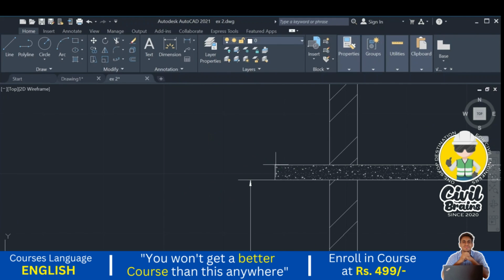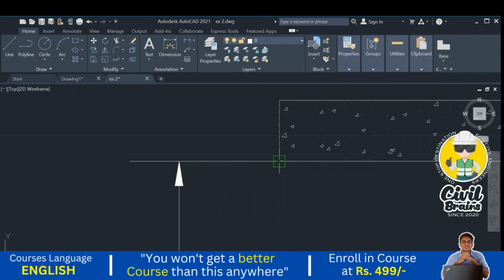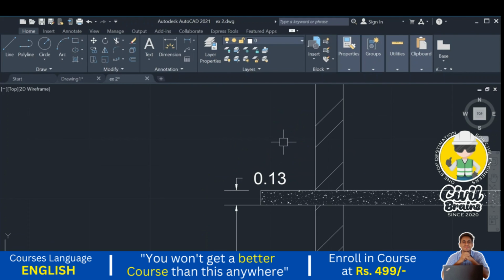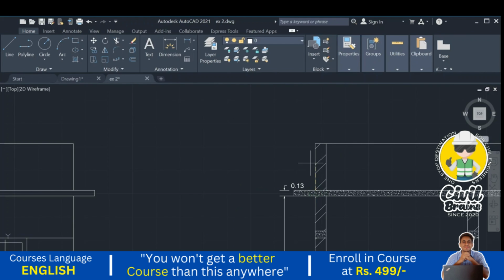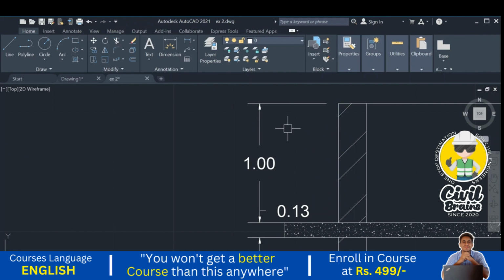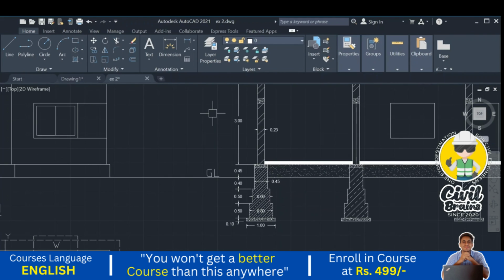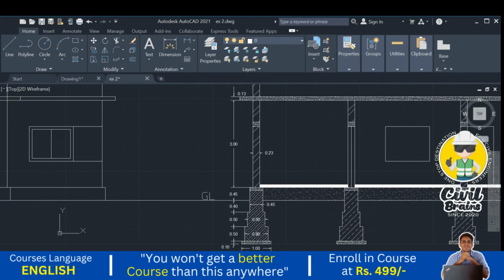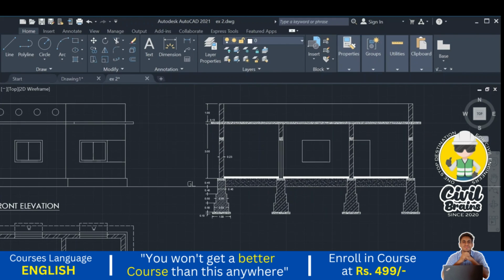Okay, next thickness of this one, that is 0.125. Okay, this is 0.125. Why is it showing 0.13? Because the fractions we have taken only 0.00, that's why. If you change the fraction, it will come properly. Now thickness of the height. Okay, so all these things we need to show, all the dimensions we have covered, correct? Next, no need to show for all the walls, only one section we need to show.